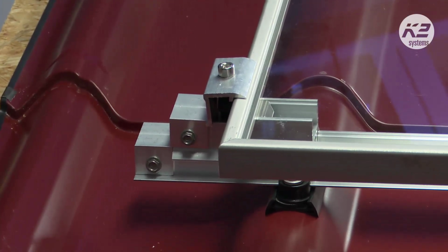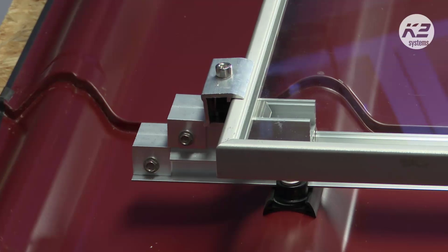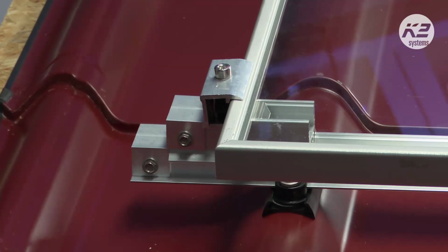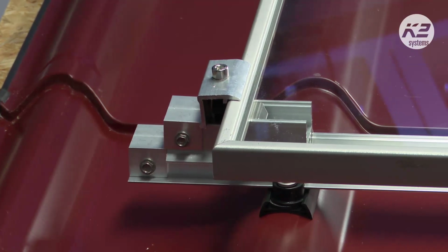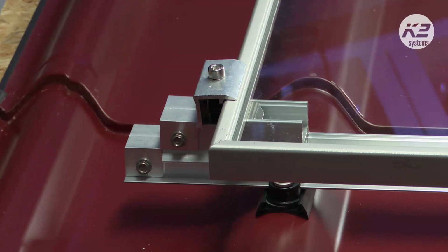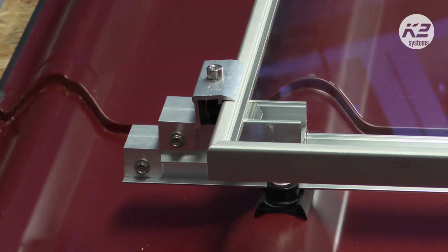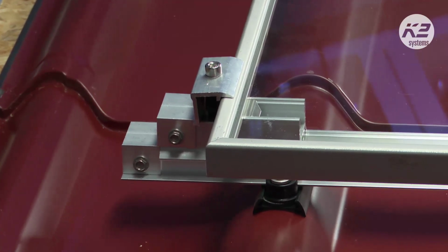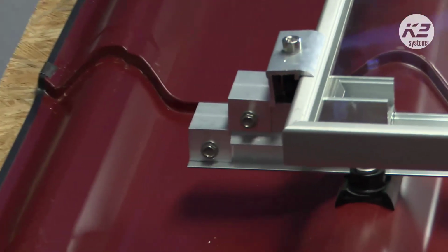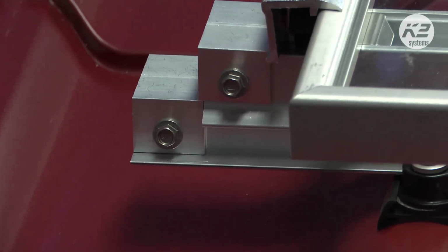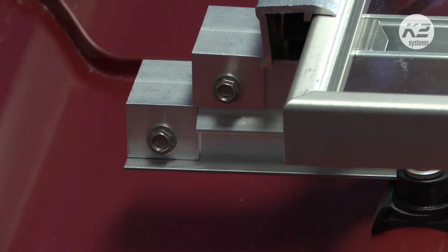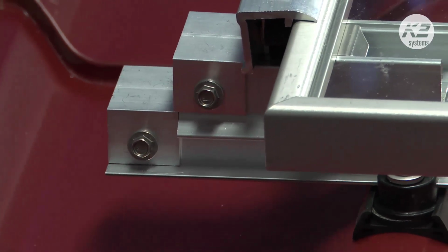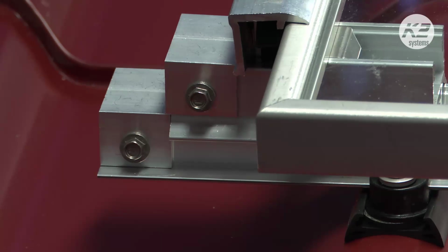It can be a little hard to align everything, and if you put this slip clip on and then you put the clamp in, you can just push the panel against it, and it's got a hard stopper to help with the installation. The other two, the ones on the basic rails, hold the FlexAdapter in place. So this end panel isn't sliding, because the FlexAdapter has no mechanical fixing to the rail. We need to just hold it in place sometimes.